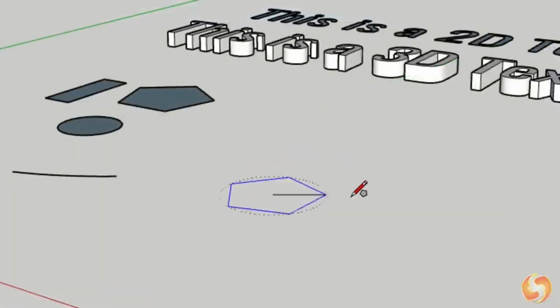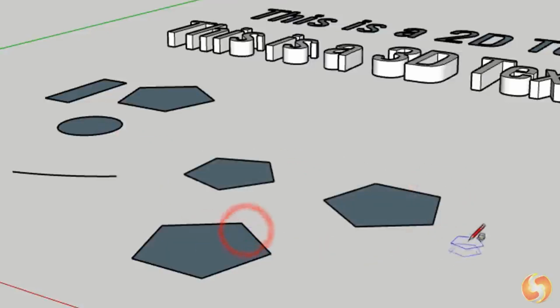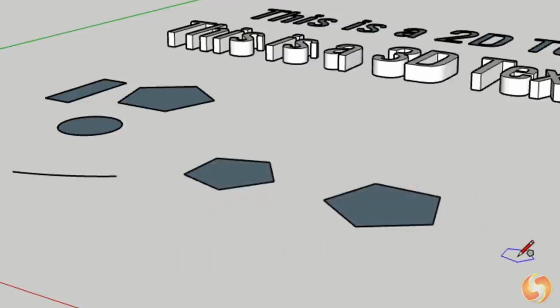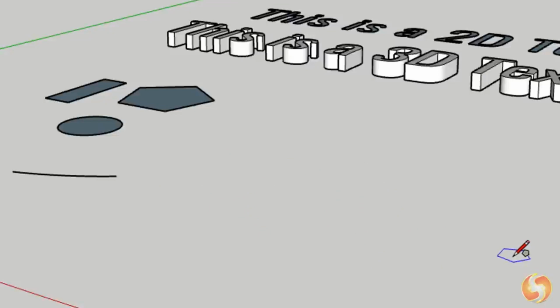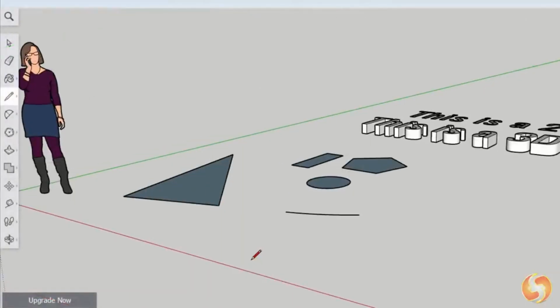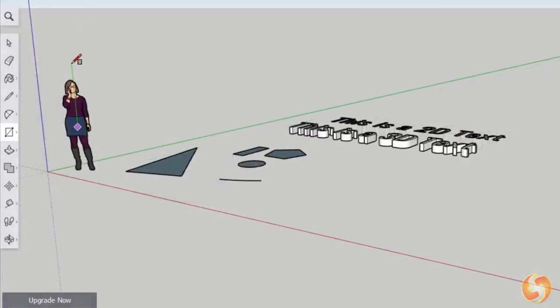To undo any drawing in progress, use the Escape key. Whereas to undo any action or modification, use Ctrl and Z. SketchUp provides several visual aids to make your drawings easier. For example, when drawing any segment, this assumes the same axis color that comes from parallel to it. And when dropping any 2D shape, this gets the same axis color that is perpendicular to its base.